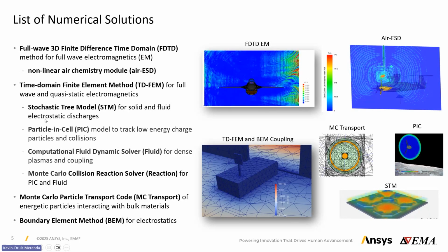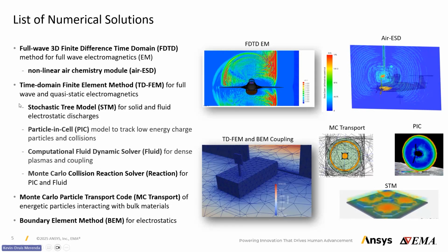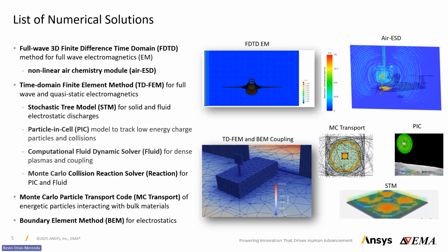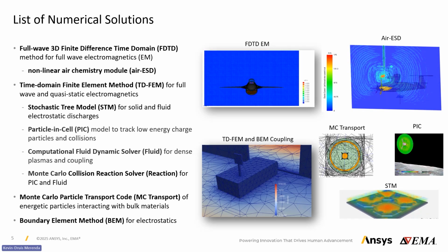This is a discharge modeling solution that relies on a provided dielectric strength for the material, and as we'll see in a little bit, it uses more of an empirical approach to modeling the discharge process. But it still allows you to model the partial discharge inception voltage, for example, or even the full continuing current through the system and the proper discharge waveform associated to the system.